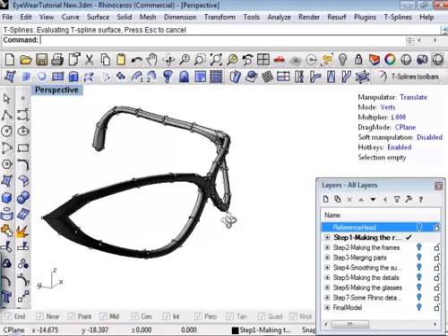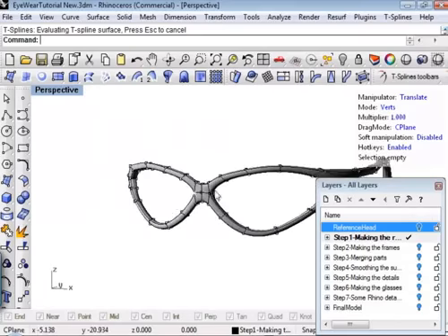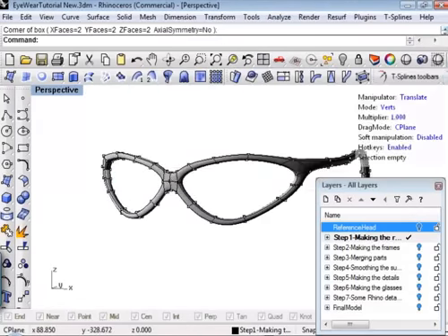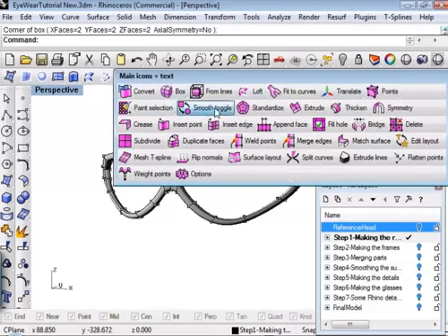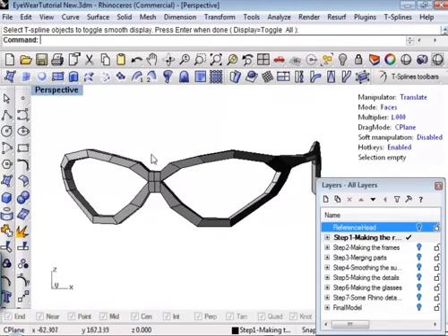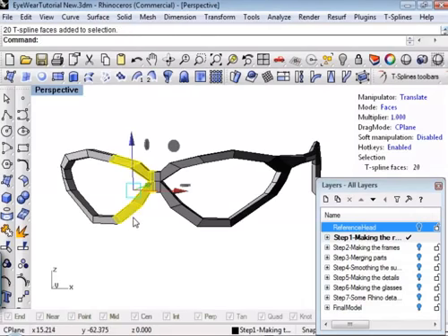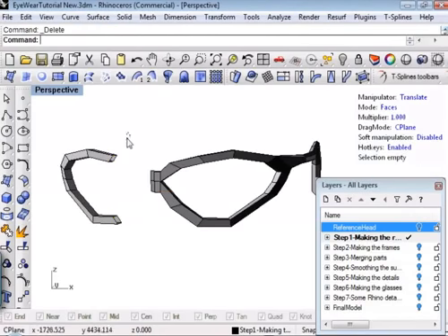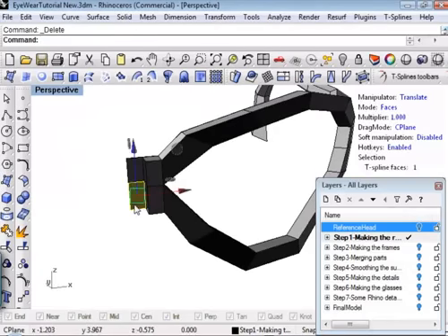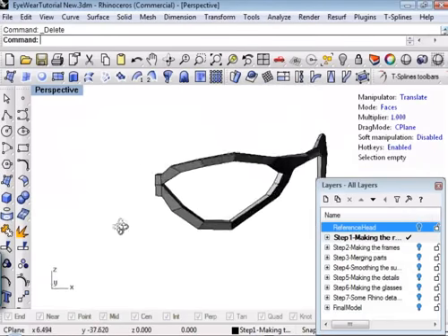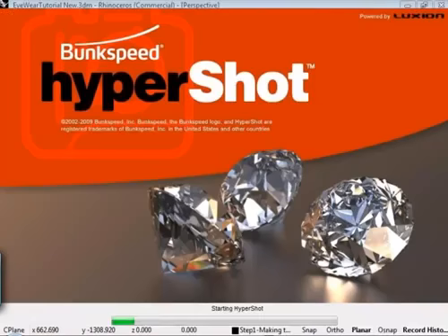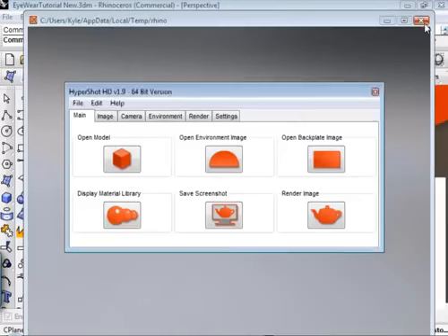So let's fix that. I'm going to go back into box mode. No, not make a box, box mode, smooth toggle. There we go. I'm going to grab my faces that are on the other side of the line of symmetry. I'm just going to delete them. Just get rid of them. And you can do this at any time. You can add or delete faces anytime you want. Now if I toggle smooth, oh, stop it. Sorry about that.